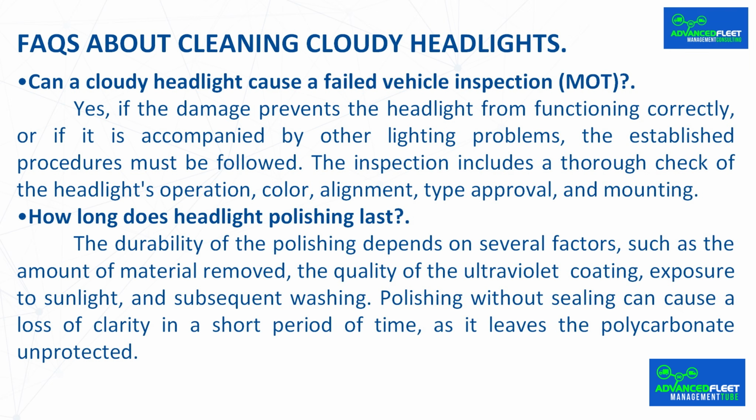How long does headlight polishing last? The durability of the polishing depends on several factors, such as the amount of material removed, the quality of the ultraviolet coating, exposure to sunlight, and subsequent washing. Polishing without sealing can cause a loss of clarity in a short period of time, as it leaves the polycarbonate unprotected.